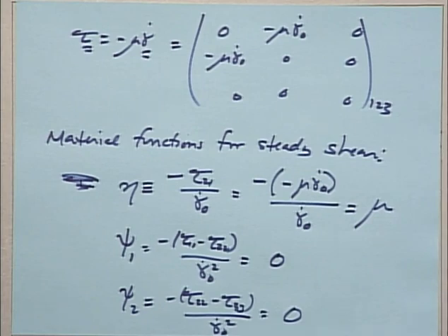So the Newtonian constitutive equation says that if you put a sample between any shear flow, it will not produce normal stress differences. It will not. It's not in the constitutive equation. Okay? So this constitutive equation is incapable of producing, say, rod climbing. Incapable. Because we saw that rod climbing required a first normal stress difference effect.